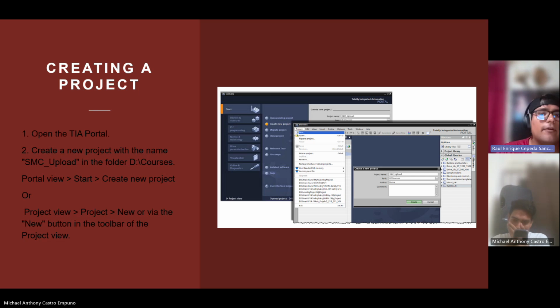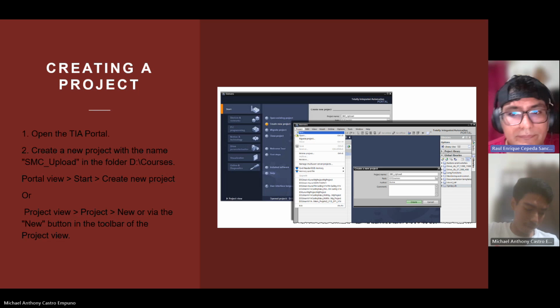Keeping the editor window in the foreground when the editor page is split. If you work with a split editor space, one of the two working areas can be fixed, attached by clicking on the paperclip. The paperclip is vertical, so that when you open a new editor, this first one always remains fixed in the foreground, and the newly opened editor always becomes the visible editor.